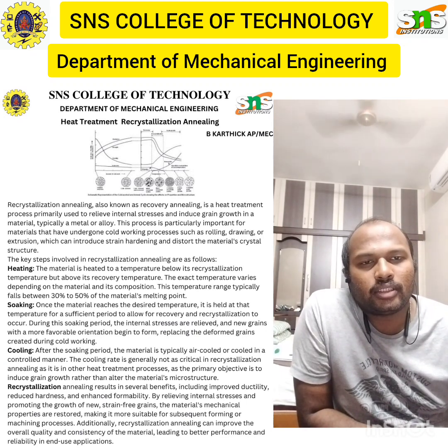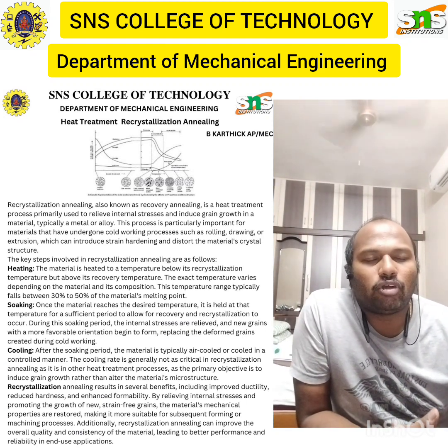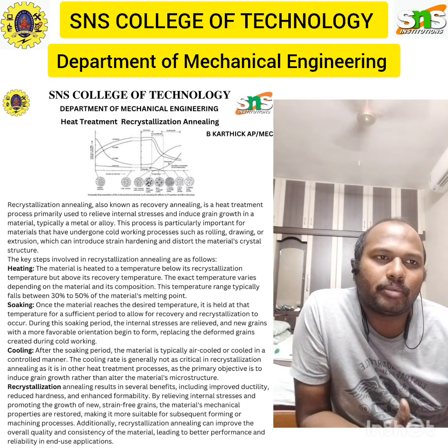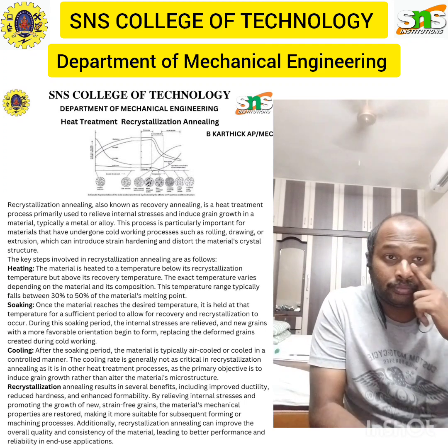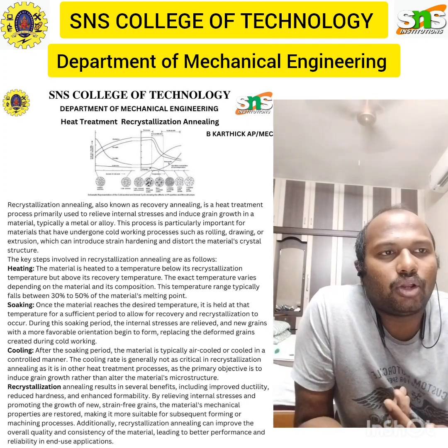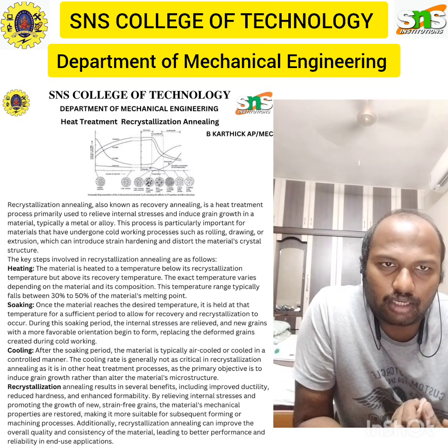Taking soaking into consideration, once the steel reaches the desired temperature, it is held at that temperature for an extended period of time. This soaking period allows the diffusion of carbon atoms within the steel, promoting the formation of spheroidal carbides.